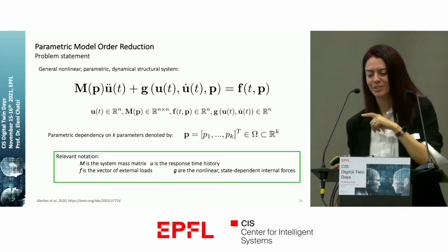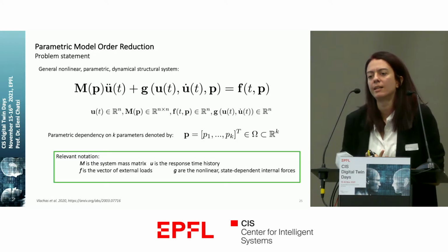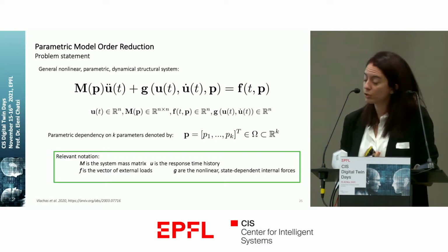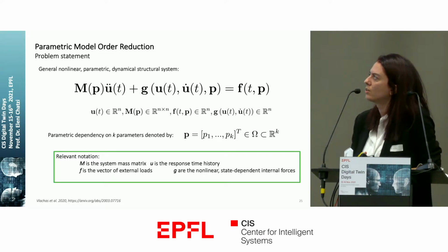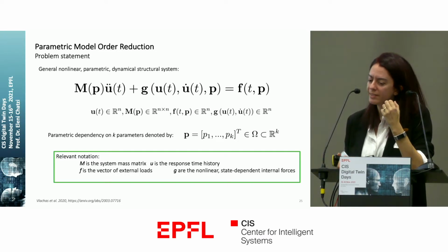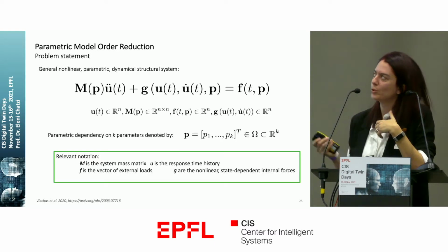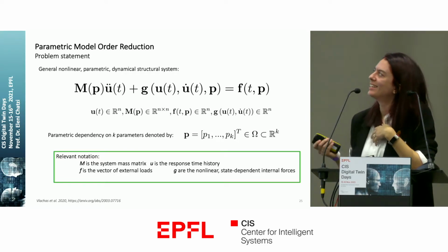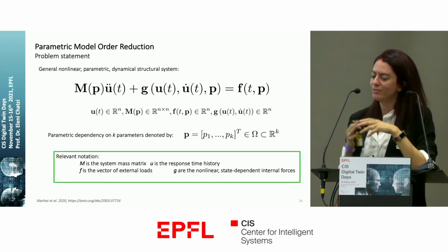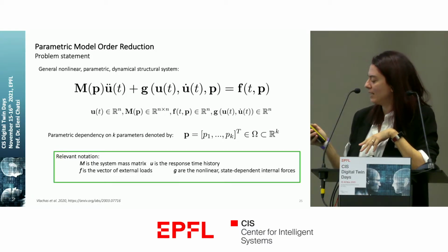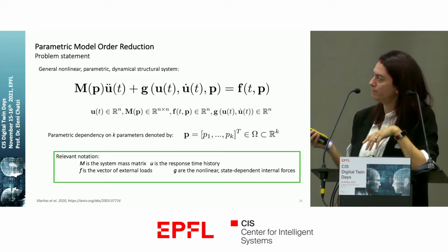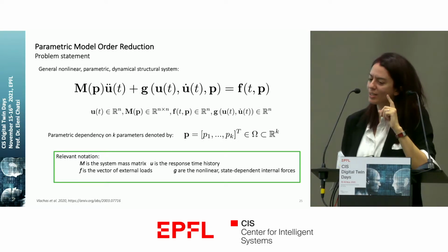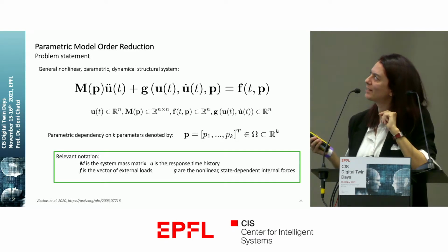Now, this kind of an approximation, of course, was trying to approximate nonlinear dynamics using a neural network approach, but another way to achieve this reduction that many researchers are also working on in this domain tries to maintain a more physical connotation in this kind of a reduced system. So again, I show you here this general equation that represents nonlinear dynamics. This is the equation that corresponded to this full field finite element model that I showed in the beginning that had multiple, maybe millions of degrees of freedom, that you see here denoted as an order n. And where additionally, in this case, the complexity is that the model depends on some defining parameters.